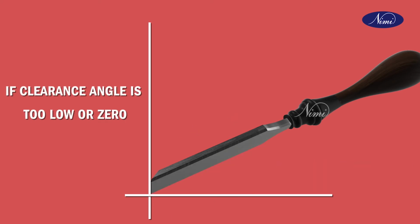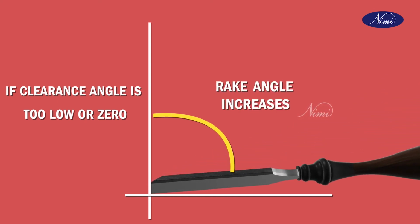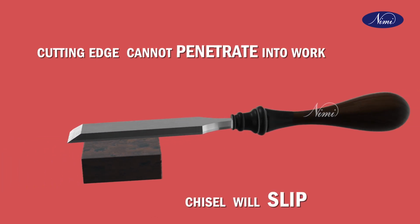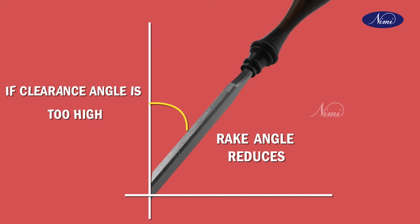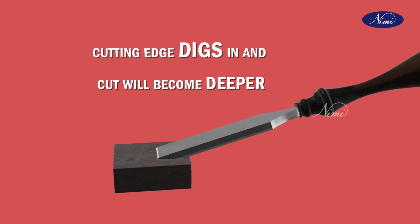If the clearance angle is too low or 0, the rake angle increases. The cutting edge cannot penetrate into the work, and the chisel will slip. If the clearance angle is too great, the rake angle reduces. The cutting edge digs in and the cut will become deeper.